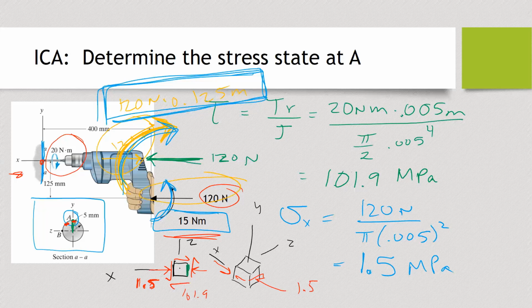But oftentimes that screwdriver is going to slip out of the head of the screw, because the thing you're relying on to resist that moment is that little bit of a connection between the bit and the screw, and it has a tendency to want to go like that. So you can maybe apply a small moment, but if you're applying too much force, it's going to slip. So if you're going to apply a lot of force, you need to torque your wrist a little bit, or apply a force that's kind of upward and over, so that unwittingly you've applied a moment.